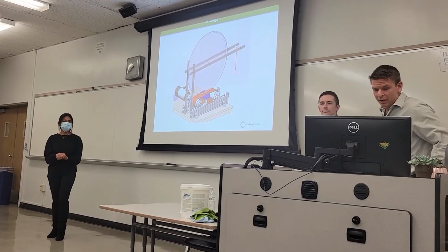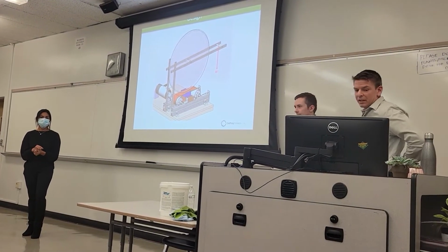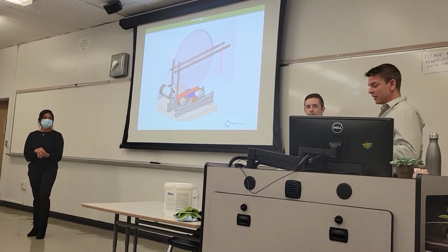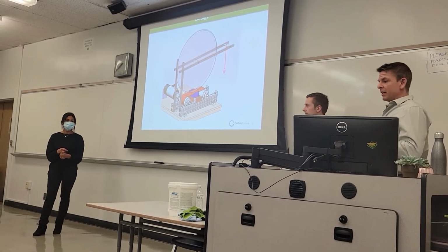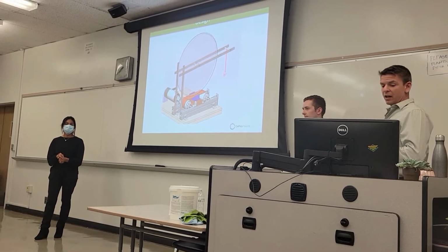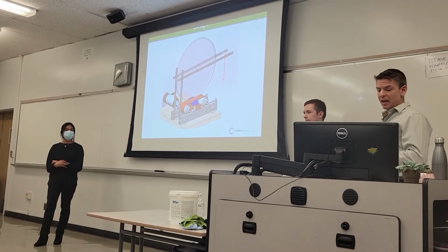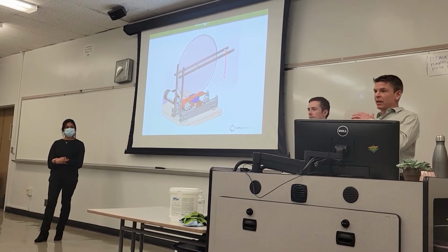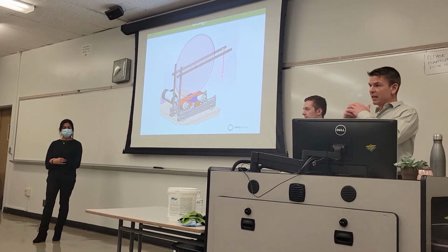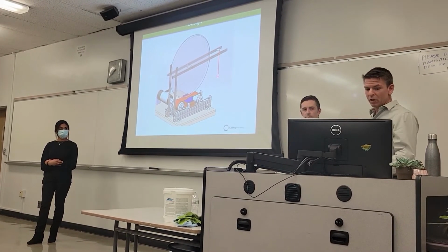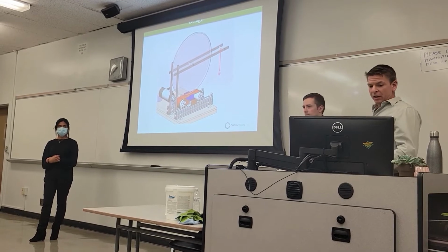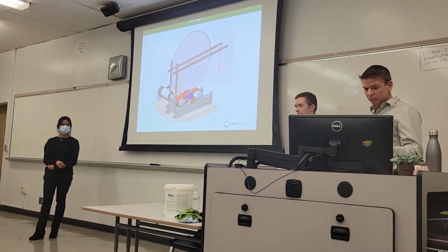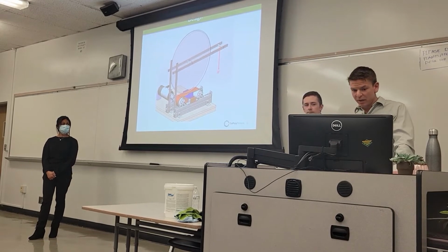Okay, so as Karen mentioned earlier, the historical testing for tires has been typically on a drum, and the problem with that is, for one, it doesn't mimic real life testing. We don't ride on curved surfaces, and the drum actually exaggerates the hysteretic losses within the tire by biting deeper into the tire. So for our design, it was important for us to create a stable, flat platform for the wheel to sit on, which is what you see here in the middle.